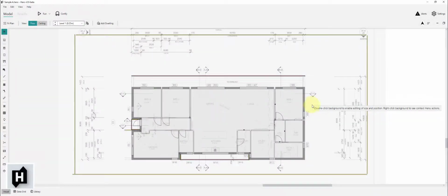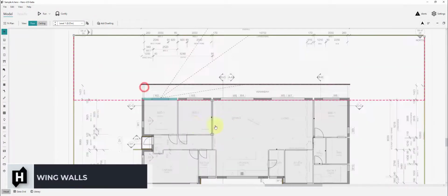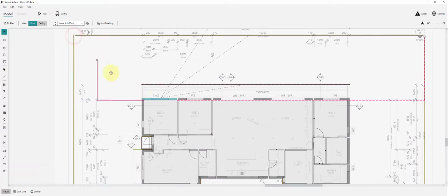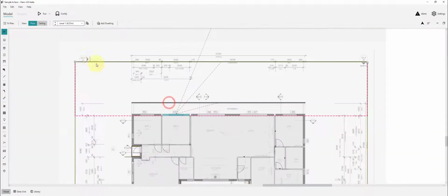In terms of visual items, next step we'll just walk through double checking our wing walls. These have obviously picked up the fences as wing walls, which is correct, but we've got some closer wing walls for this north eave that are going to have more impact as we would judge it in terms of shading than a fence. So we just drag those wing walls back in. It's always worth checking the automatic wing walls that are picked up just to make sure they're all sensible.